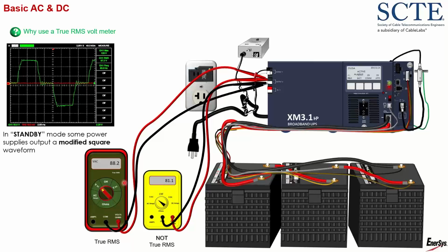So, you know, I'm not saying you have to use a true RMS voltmeter on your cable plant. I'm saying if you don't use a true RMS voltmeter on your cable plant, you better understand how those different waveforms affect your non-RMS voltmeter.